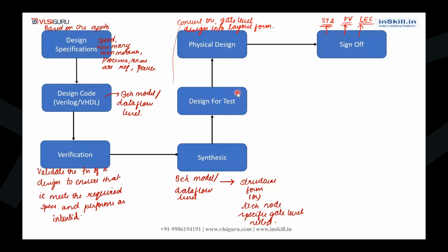So our design is undergoing a lot of changes in each stage. That's why LEC is done, to check whether the final design is logically equivalent to the original design. LEC will be performed after each step, like after synthesis, after DFT, after PD; it will be done after each stage.